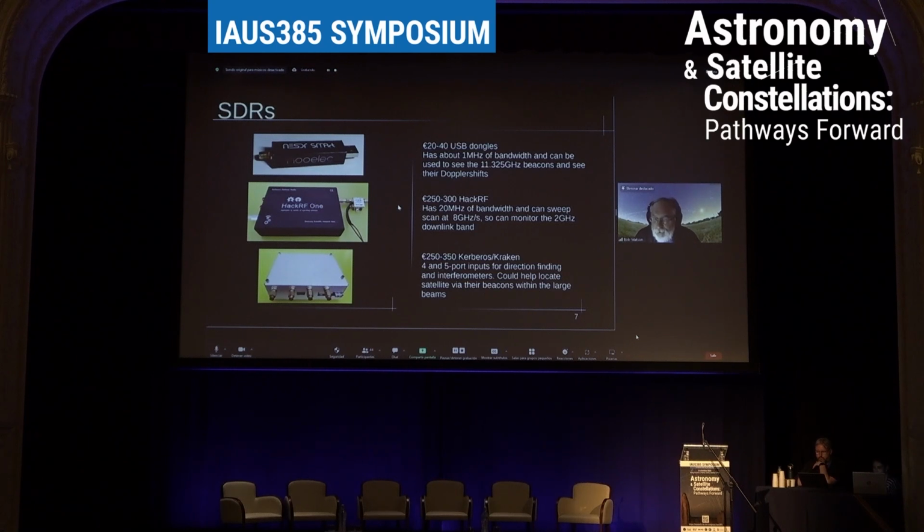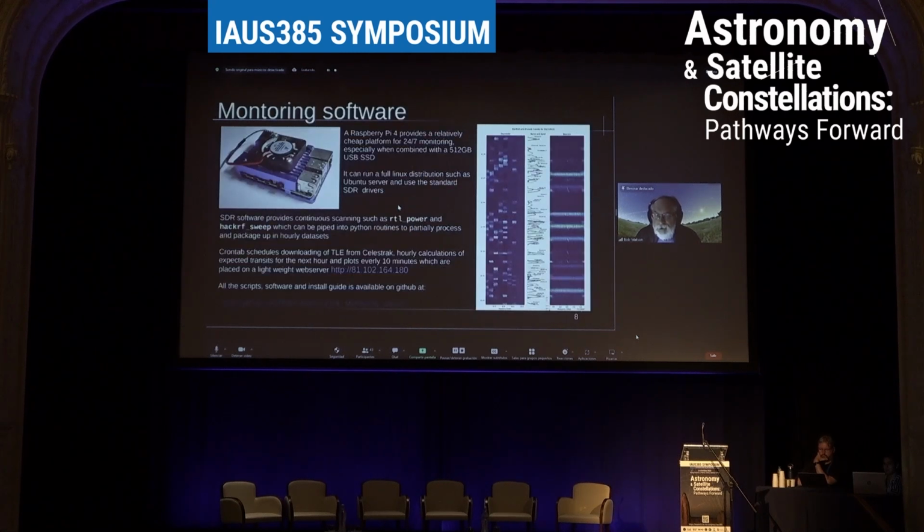And I've just started experimenting with interferometry, in which case you can get this, slightly old now, KerberosSDR, and a Kraken is out, which basically has 4 of these dongles all synced up together, so you can take data simultaneously and get direction finding. I'll come on to that a bit later.